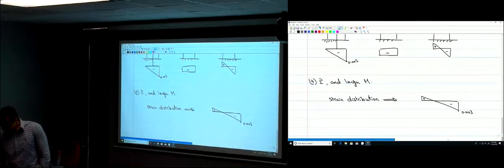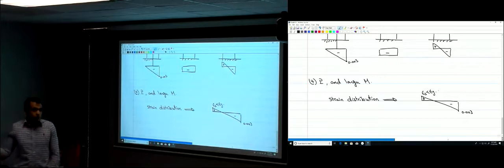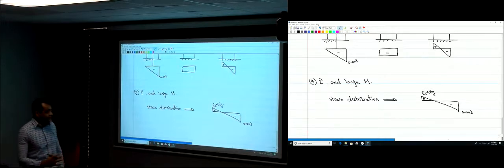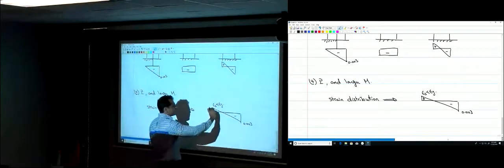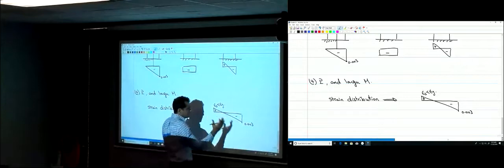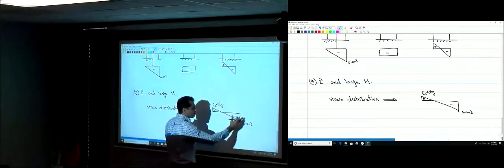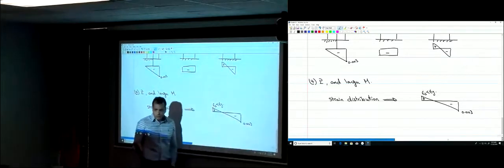In this case, let's say the strain here, where the steel is, epsilon s, is less than epsilon u. But here, again, the column will fail, even if the steel didn't yield, okay? The steel here has some tensile strain. It didn't yield, but the failure will happen due to the crushing of the concrete on the compression side.